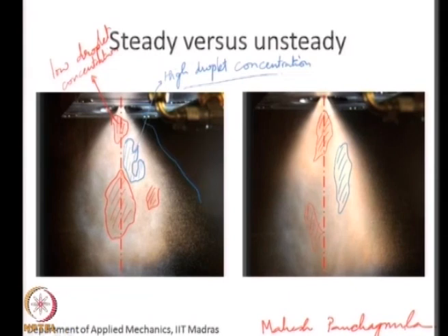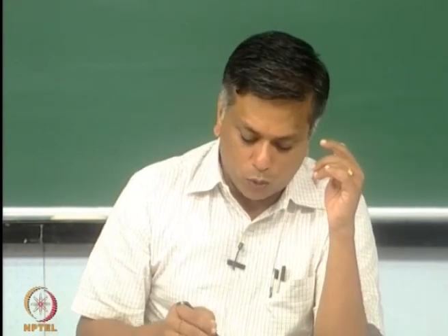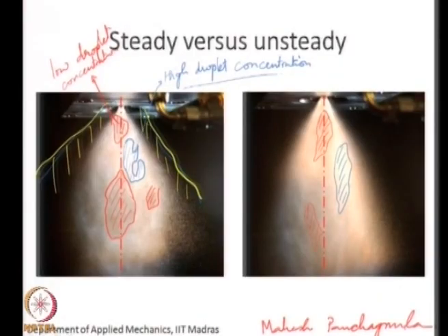So, right around here, I have a co-flowing stream of swirling air, and this swirling stream of air interacts with the drops that are formed on the periphery of the spray. And this interaction between this swirling air stream and the drops is responsible for these lean and rich spots.